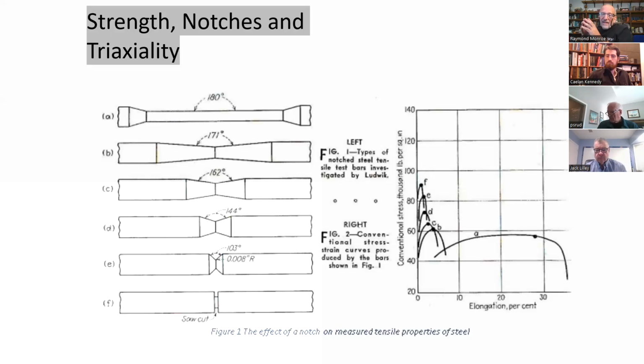That is why in the Navy, when you're welding together HSLA 115, you use an undermatched weld rod, and it works fine because that undermatched weld rod is actually like diagram F. You've got a very narrow band of material with higher ductility and lower strength, right, and you can't do it.